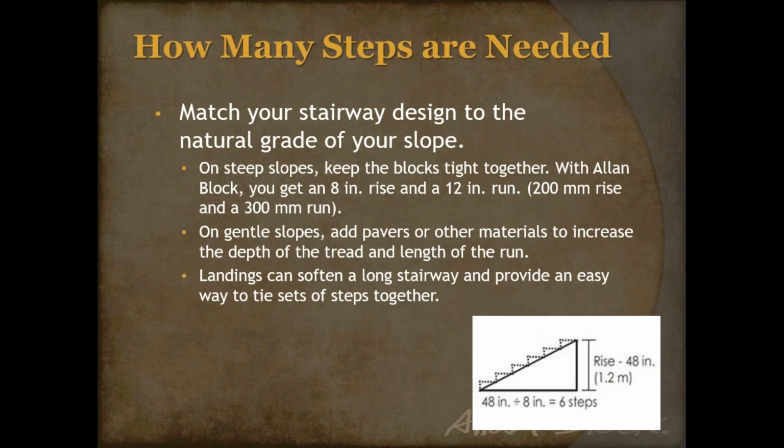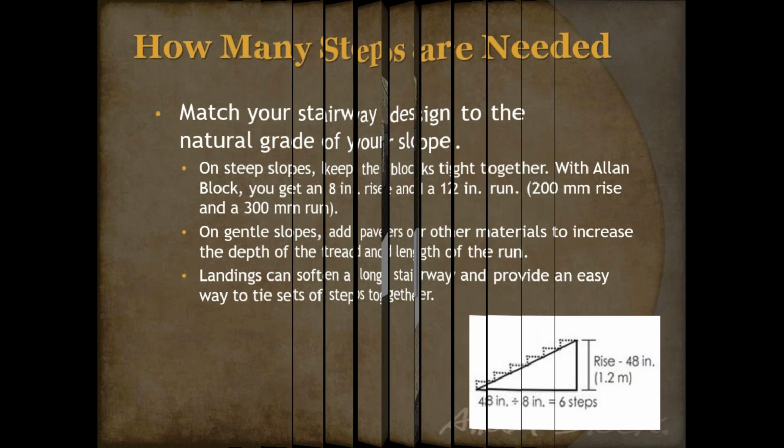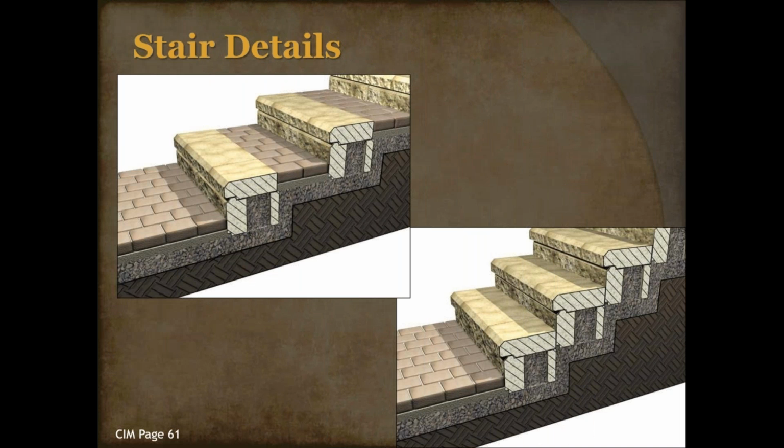All right. Now, if I can spread that out over a gradual hillside, then I know my treads could be a little bit wider. If it's got to be tighter together because they just don't have the distance, then you're just doing nothing but caps. So that's the key, right? You know the tread height, or you know the riser height, that's your block. Then you've got to just determine what is that tread depth. And that's the element to the stairs that you need to determine.